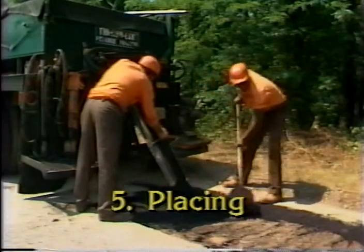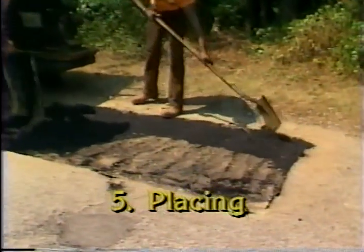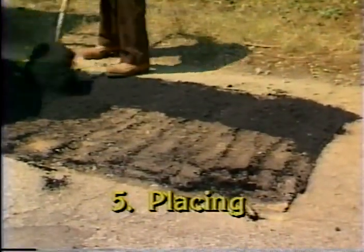5. Place the plant mix asphalt evenly in a maximum lift thickness of 3 inches. Take care when handling the mix to avoid segregation of the material.